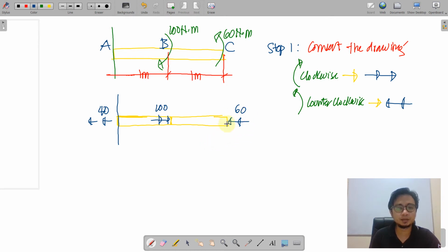Like this one, we are in equilibrium, so therefore the restraining force to counter this 160 is on the restraining support here at A. So applying that, of course, again we compare 160, 100 is greater, and that will be towards the right, so that your resisting force should be equal to 40 towards left. By that, we can now proceed to the second step.